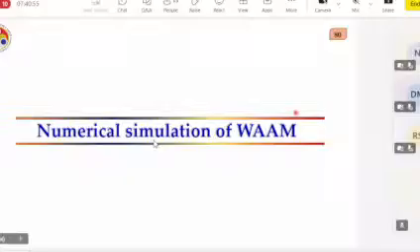Another way is we can directly use this model and put a convection heat transfer coefficient so that it represents conduction only. At the bottom plate, I'm going to put the convection very high, maybe 400, 500, something like that, similar to the conductivity of the material. And for the edges, all the walls will lose heat by convection and radiation, so accordingly we put the properties around these walls.